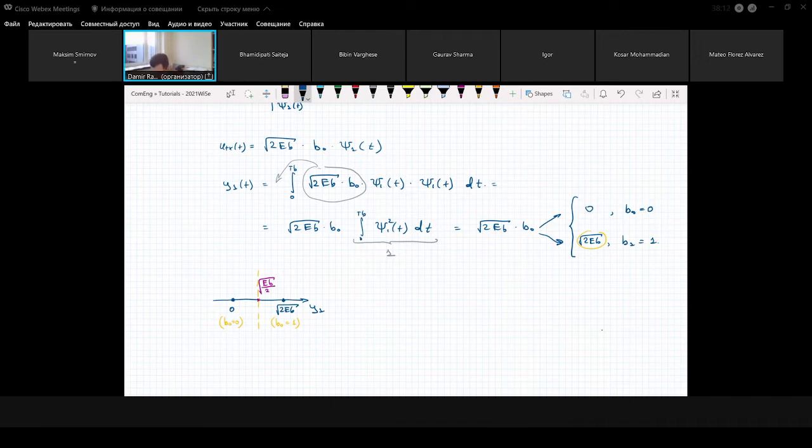I mean, there is nothing to explain about orthogonality. I just said that because we use orthonormal basis functions, but for this specific example, we have only one basis function. Nonetheless, because we use orthonormal basis functions, many things will be simplified. And when you write the received signal after processing, typically it's just the same value as in the signal space diagram because of all these measures that we take, taking into account orthogonality and orthonormality.